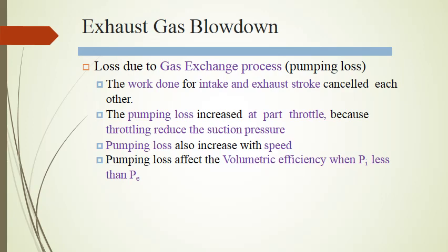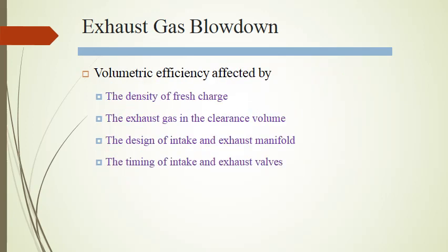The gas exchange processes affect the volumetric efficiency of the engine. The performance of the engine to a great deal depends on the volumetric efficiency. The volumetric efficiency is an indication of the breathing ability of the engine, and it is basically defined as the ratio of the volume of air actually inducted at ambient condition to the swept volume. It may also be defined on the mass basis as the ratio of the actual mass of air drawn into the engine during a given period of time to the theoretical mass which should have been drawn in during that same period of time, based upon the total piston displacement of the engine and the temperature and pressure of the surrounding atmosphere.